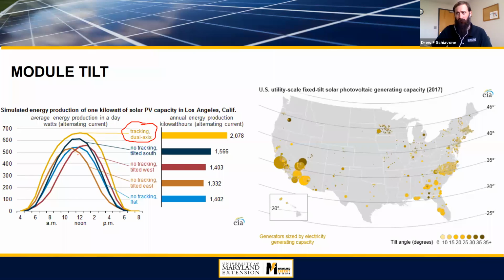What I would say is, just make sure you're facing in the right orientation, and make sure you're close to the ideal 39-degree tilt here in Maryland. You'll see a lot of commercial operations in the map on the right, big utility scale production, so not quite what we're talking about here. But even in this map, the utility scale systems are not exactly having optimal conditions.